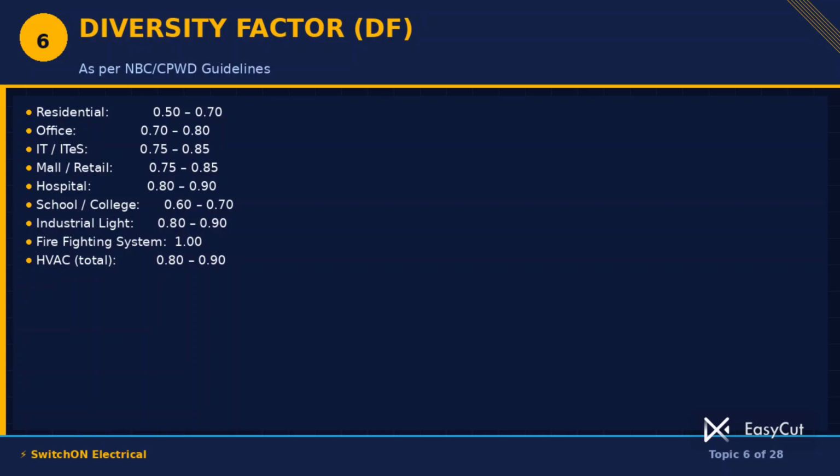Then from 6 to 8 maximum load will run. Then from 10 to 4:30 most of the people will go to office or college. At that time very less load will be there. On that basis you have to consider the diversity for other different areas.